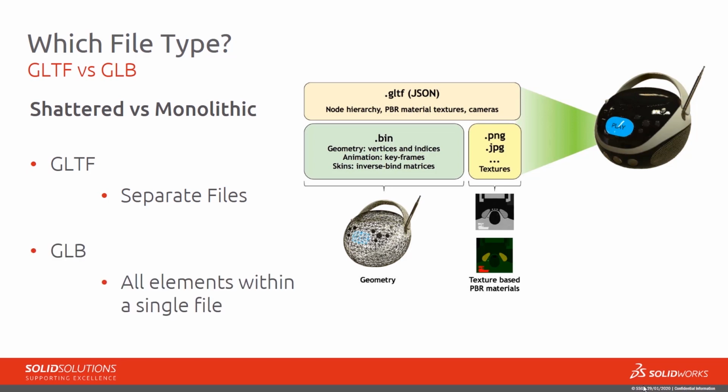Compare this with a GLB. This is all these items encapsulated in one single item. So imagine doing a pack and go of your SOLIDWORKS assembly. That's what we're doing with GLB. We're neatly tying up all these files into one single item, one single entity. Now either of these can be accepted by various different XR applications, so either file format should be fine, but check upon your requirements with the other bit of software.